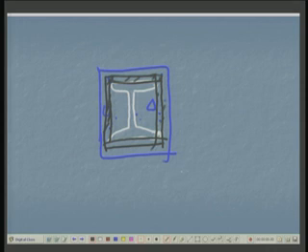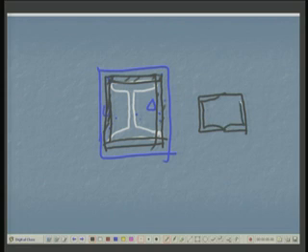Sometimes we have what is known as a water filled column. For example, in the column systems, like this, this channel is made into a box; this is the channel section. This is used in very tall buildings. You have water filled columns, and all such columns are connected together, and you have a vent at the top for evaporation, etc. These are used in very tall multi-story buildings.